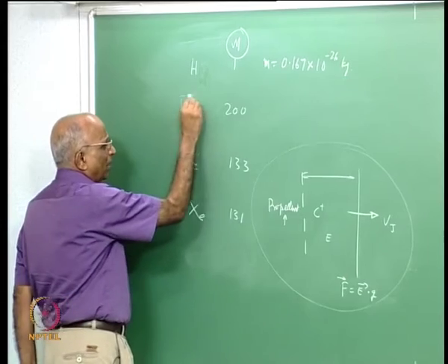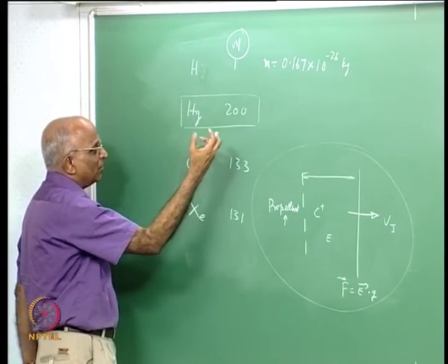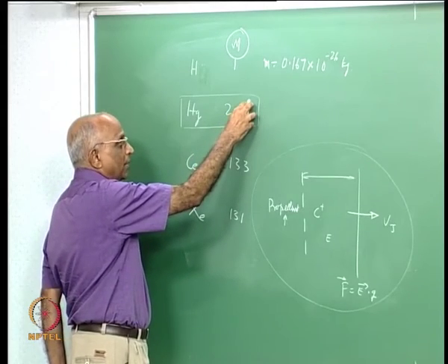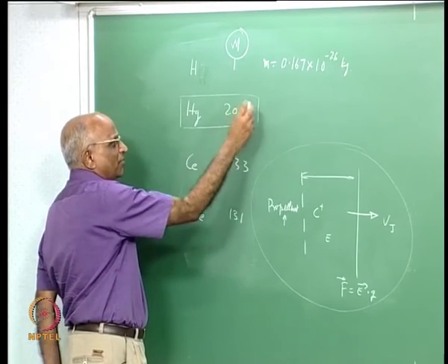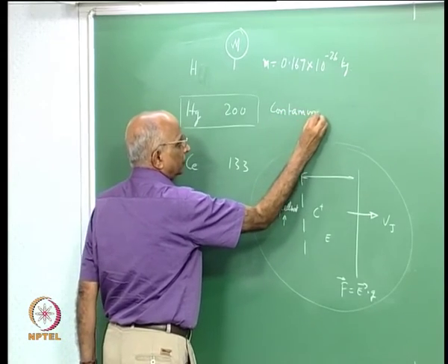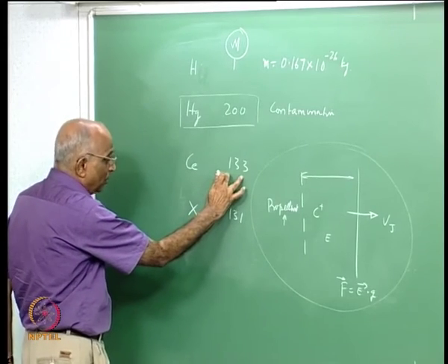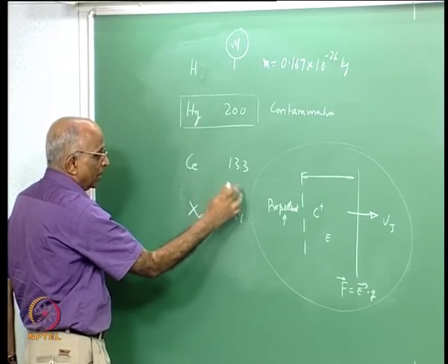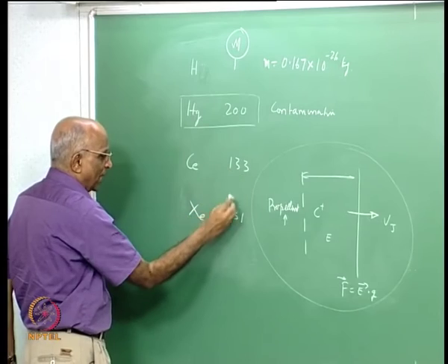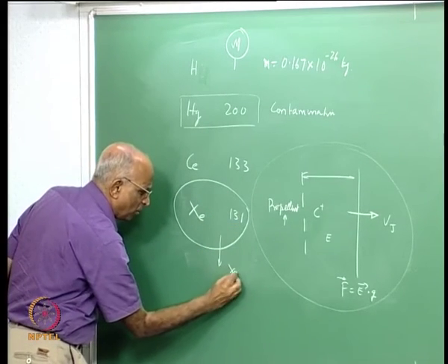Mercury is a liquid metal, but its vapor is something which is dense, and when it is used in spacecrafts it coats the surfaces of spacecrafts and causes contamination, whereas cesium is a little reactive. Even though it can be easily ionized, it is more difficult to use, and the general trend today is to use xenon, which is a noble gas.